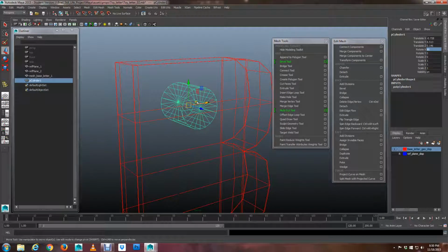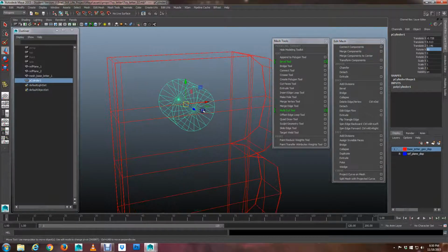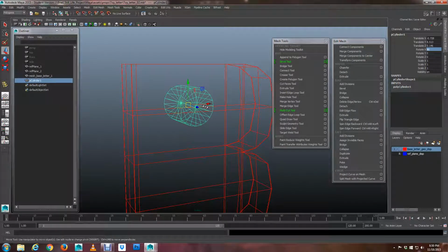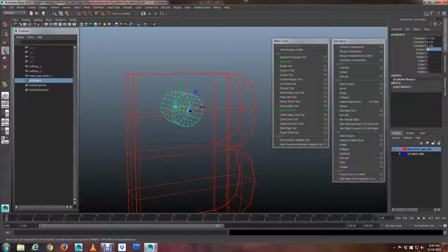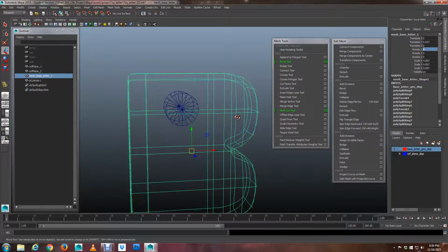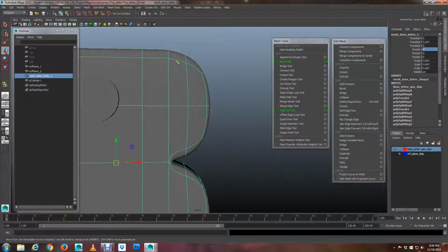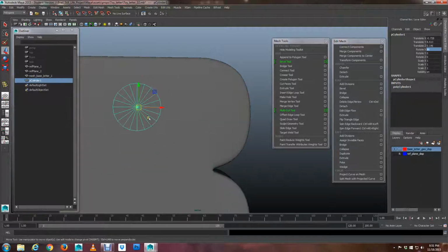From a production standpoint, I don't want things to be super high polygon. You always want to keep your poly count as low as possible. So it's a bit of a trade-off. Your poly count needs to be high enough so that surfaces, like this guy, solve properly. If I didn't have this edge in here, the way Maya would calculate this, it wouldn't handle that sub-D very well. It wouldn't subdivide it very well. But since I put that in there, it doesn't have to work very hard to smooth out this corner. So yeah, you need subdivisions, but this is overkill.